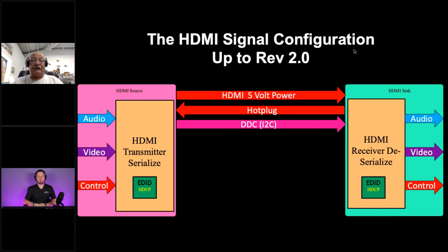So there's a clock and there's a data line. They have to synchronize with each other, but the integrity of that data line's got to be pretty good. And that's a whole other story. We'll do it maybe one other time. But what HDMI did is they gave the specification of that in capacitive loading.